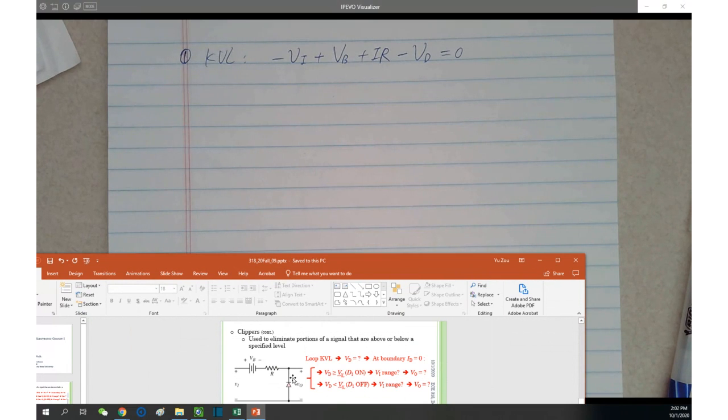If you reverse the VD's polarity, then you need to say VD less or equal than V gamma, the diode is on. So remember, don't mess that up. Anode, which is the bottom here, must be the positive. Does it make sense? Very, very critical.